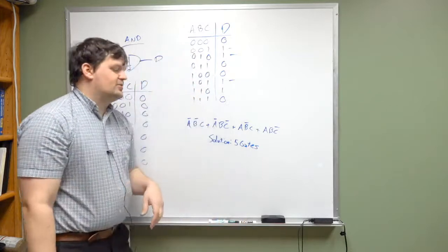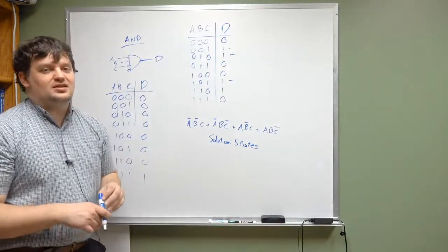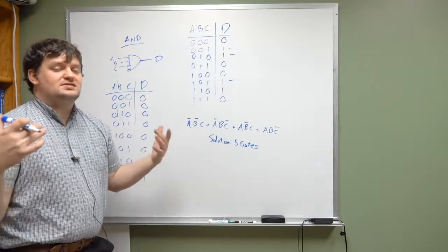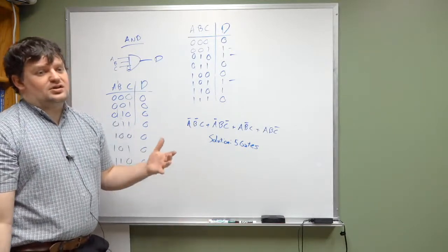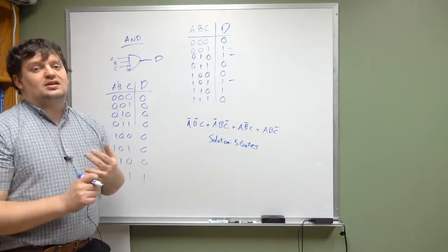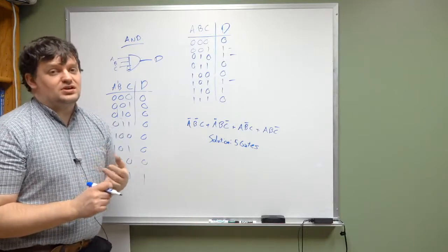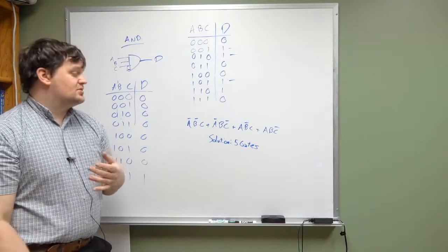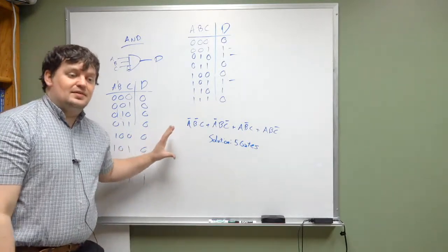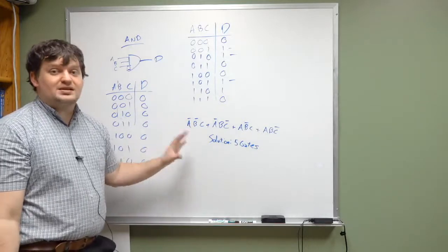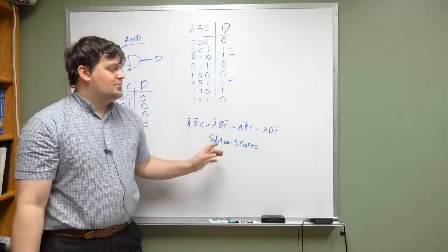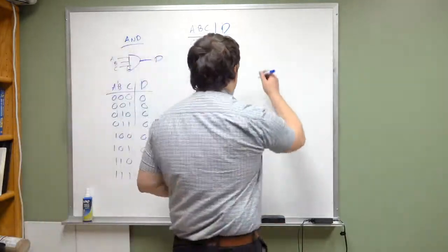As we talked about, if you've done your reading assignment yet, you know that you kind of want to minimize the number of gates, because the number of gates that you have is directly proportional to the power consumption and the time to completion of the circuit. If you reduce the number of gates, you're in a better place. So this here is workable. It's a correct answer, but it's a very inefficient answer. A better way of doing that is to look at a Karnaugh map.